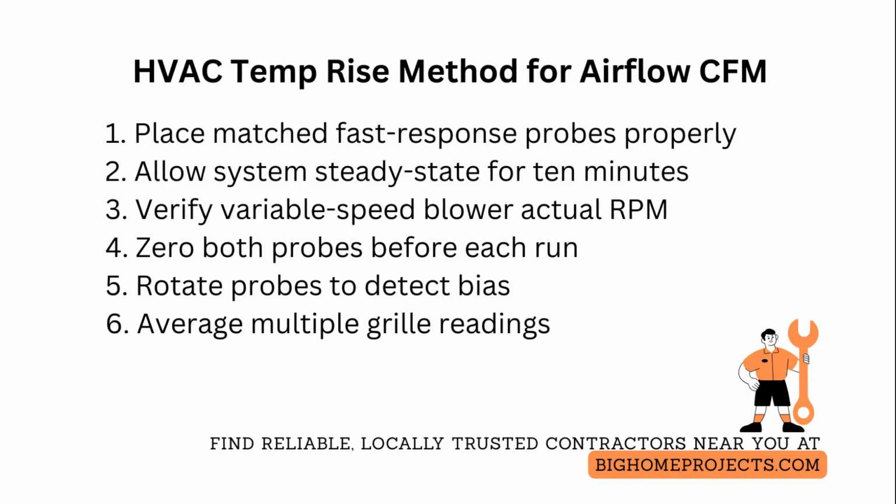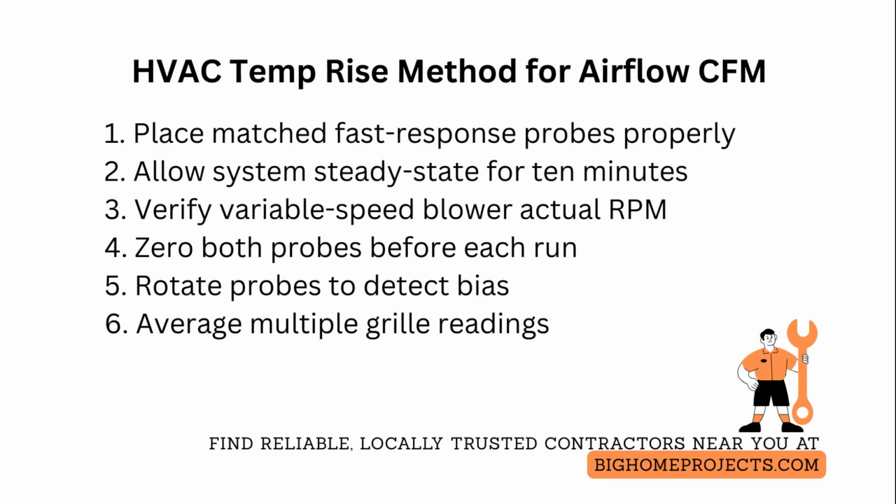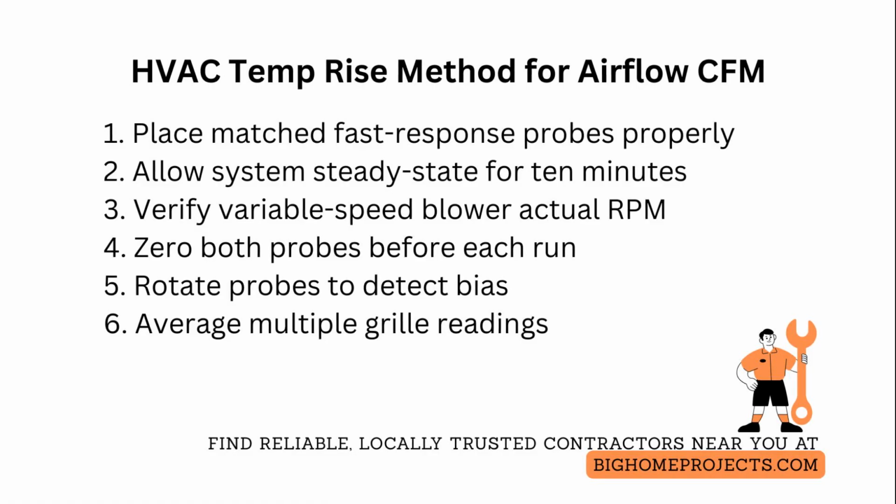Always allow the system to run at steady state for at least 10 minutes after start and check that the blower speed and static pressure are stable. Note that blower motors with variable speed drives need their actual RPM verified because factory labels can be misleading.